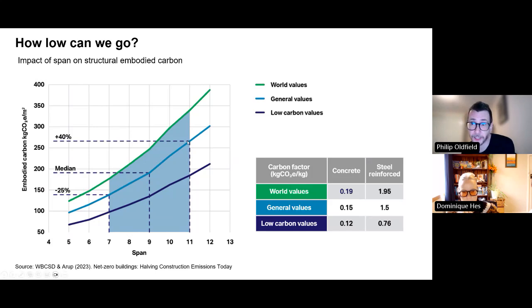Now that becomes a design challenge. That's an architectural challenge. It's not just a material substitution challenge. It becomes a conversation with the client about how they will lay their floor out, their commercial floor out, with more columns. I'm regularly telling my students and architects, we need to hug a column, you know, make columns great again, because it's one of the simplest ways we can reduce embodied emissions, because in multi-story buildings a huge amount is in the floor system, in the floor slab. So anything we can do to reduce that will have a big benefit.